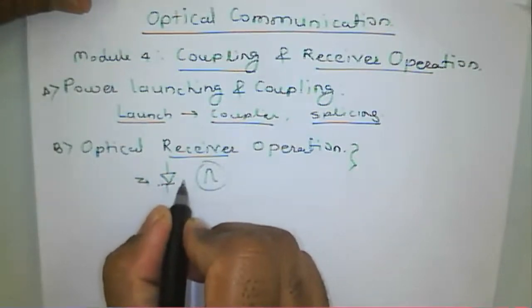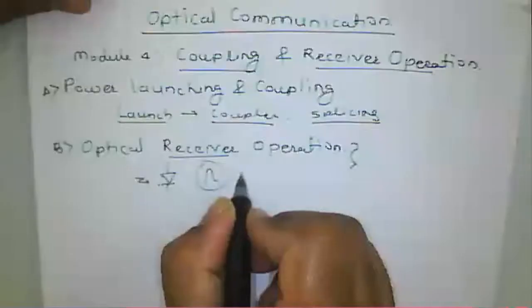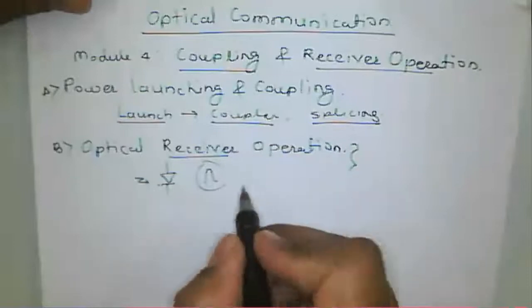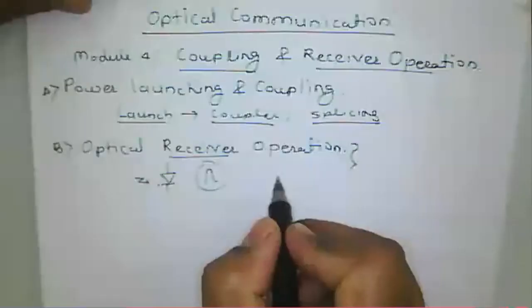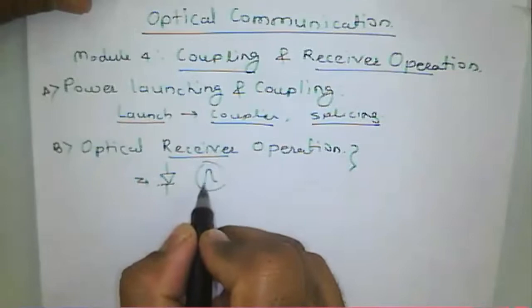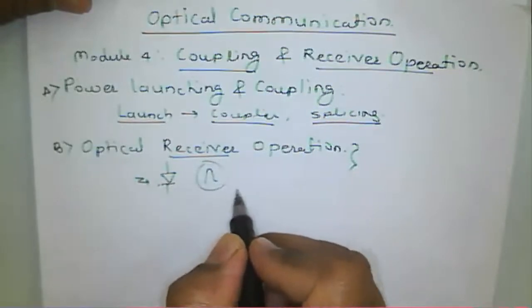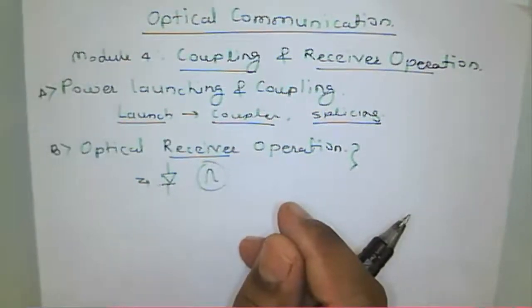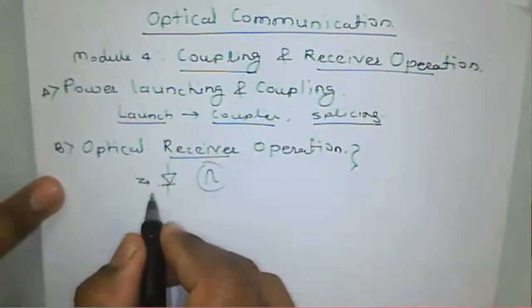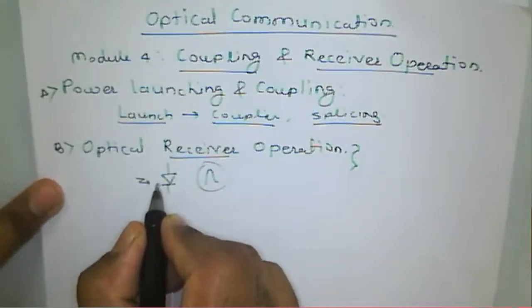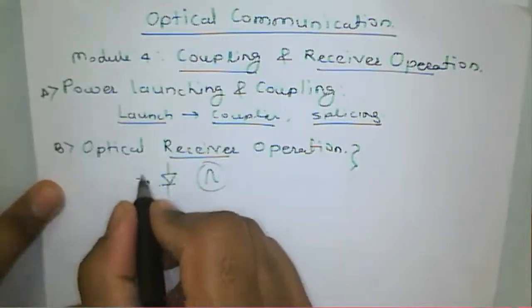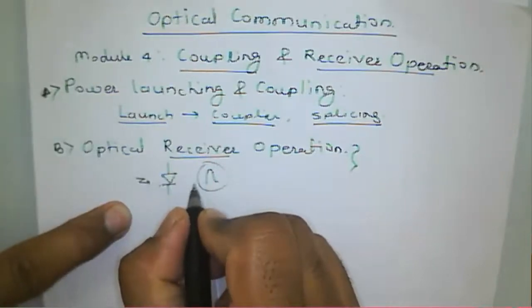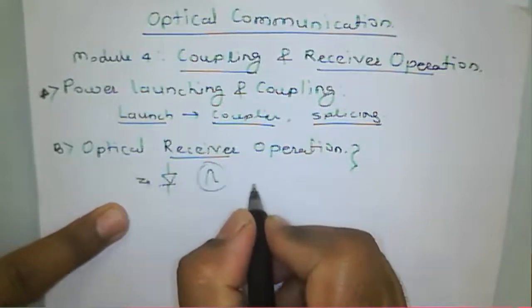Because your circuit, your amplifier, amplifies that current pulse. If the current pulse level is not large, it has some noise, and the amplifier will amplify that noise too. That's why the detector must detect the lowest possible photon energy, but produce a current pulse with low noise.